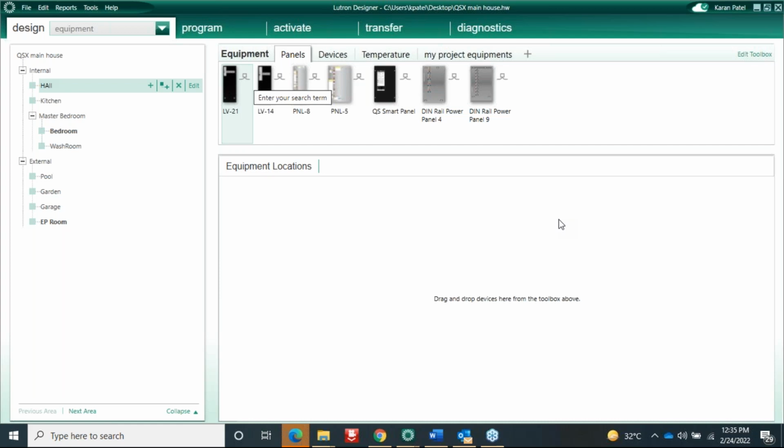It cannot work without adding that extra device at all. No, it will work, but it will be dangerous for the module. There are chances that inside, because we are using a MOSFET inside the module, it may get damaged. So we only ask you to put phase dimmable loads on it, phase dimmable mode.